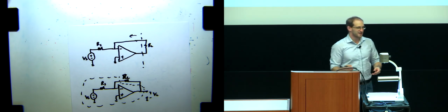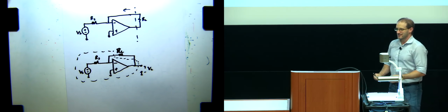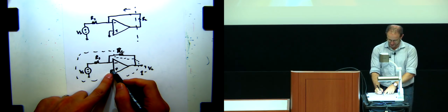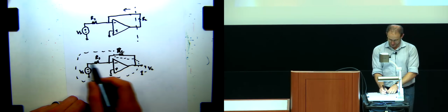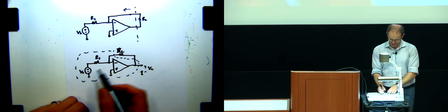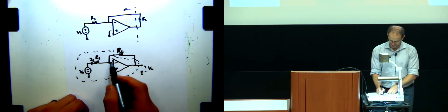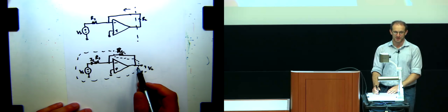Right? So all along, and in fact, when we analyzed the inverting op-amp amplifier, I assume the way you did the analysis was you said, okay, I invoke golden rule number 2. I see that this is 0 volts. That means the voltage across this resistor is just Vs. That means there's a certain current, IL, flowing through here. That current flows through this resistor. And from there, you directly compute what the voltage at the output would end up being.